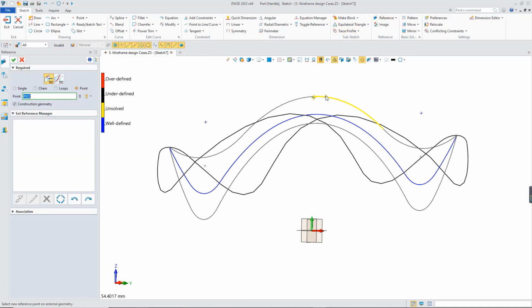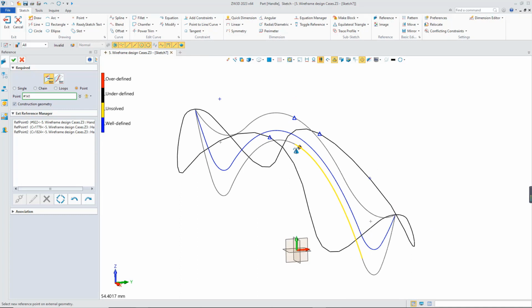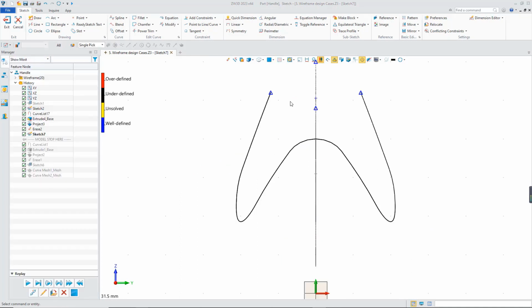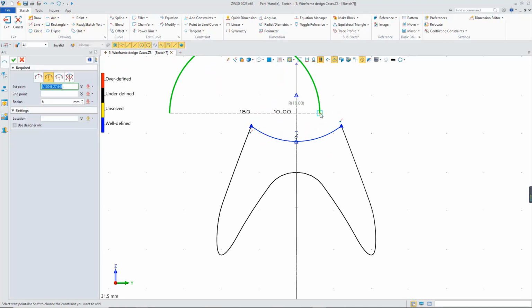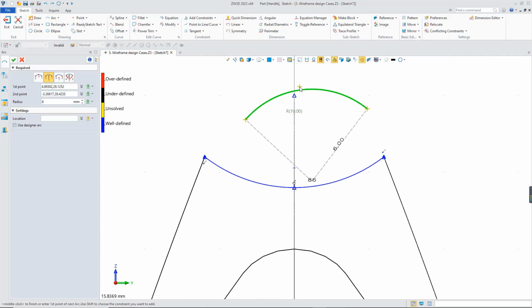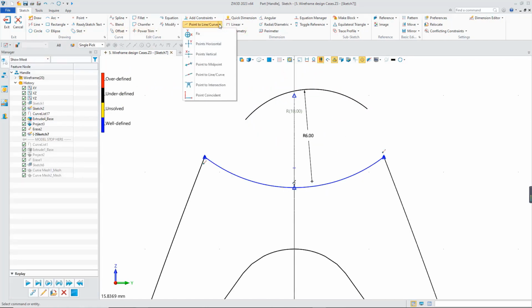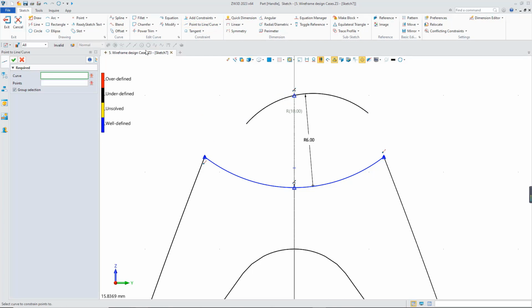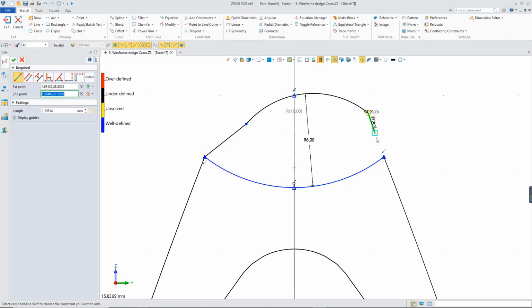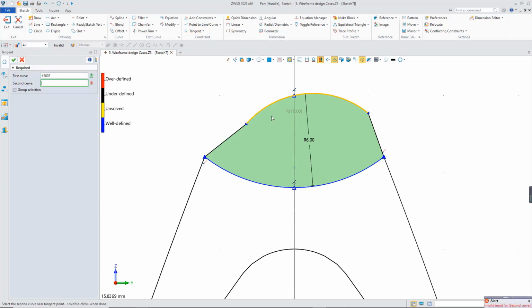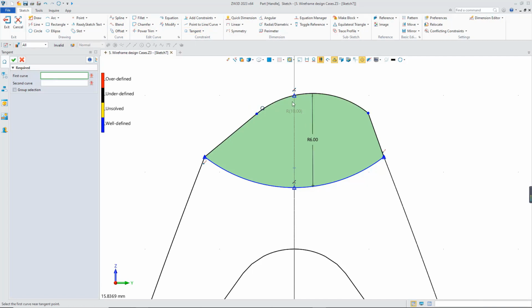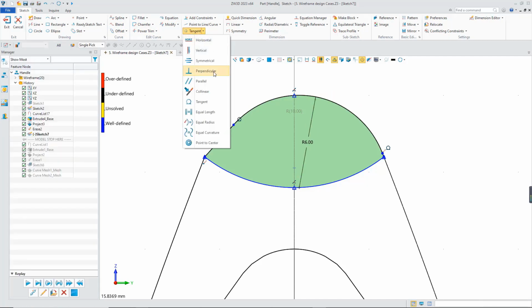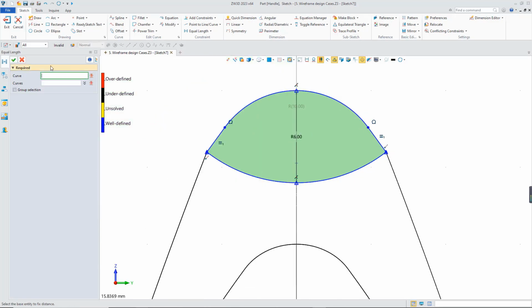Create 4 reference point by using the reference tool in Sketch module, which will be used in the further drawing. Draw 2 arcs with the specified radius. And make it cross the reference points. Draw 2 lines to connect these 2 arcs. And add the tangent constraint between arc and lines. Then, make the length of 2 lines equal.